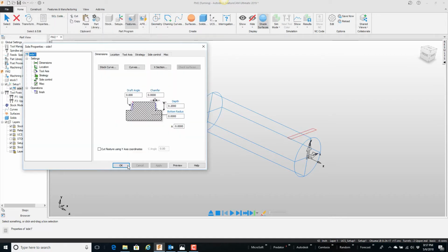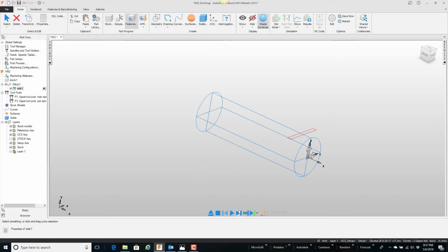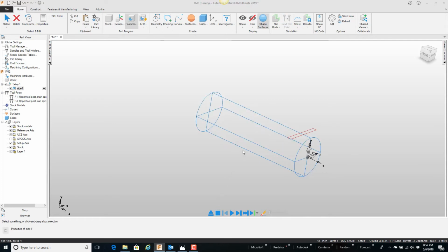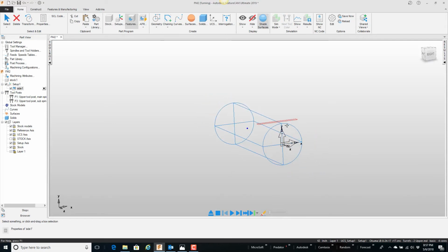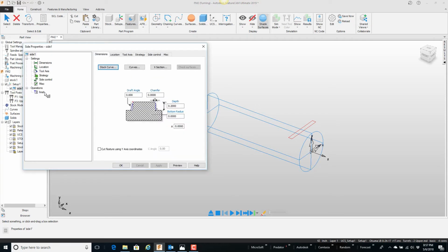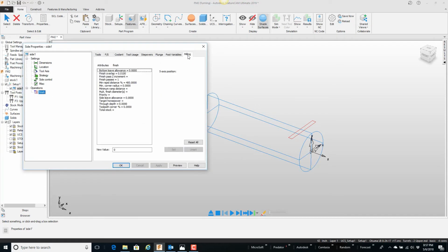So right now, if I simulate, the tool comes in from the end. Actually, it does come in from the end, but there's no material out there. Good little lesson. There's no material for it to cut. Unless, just so I can show this, if I went to finish milling and said total stock was 0, basically it's the same thing I was showing in another video.